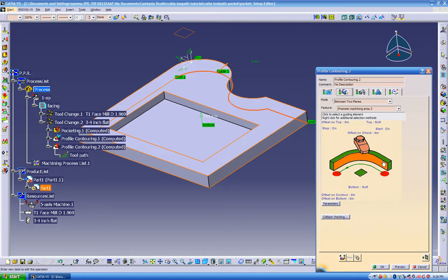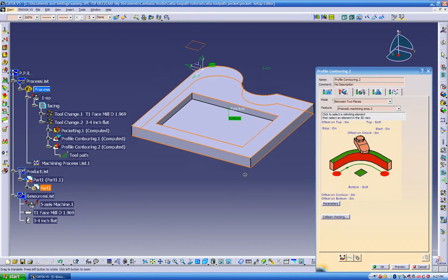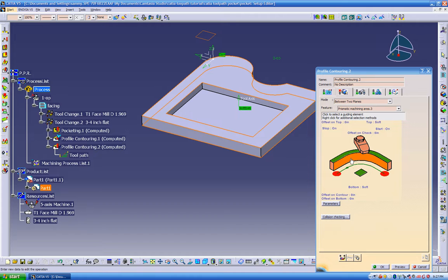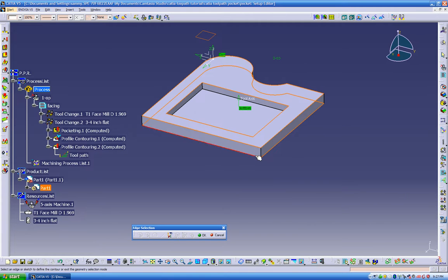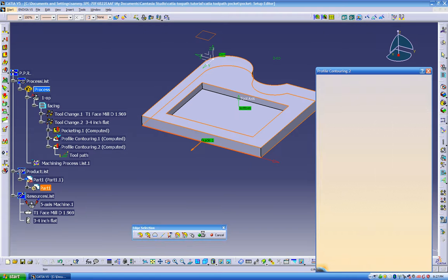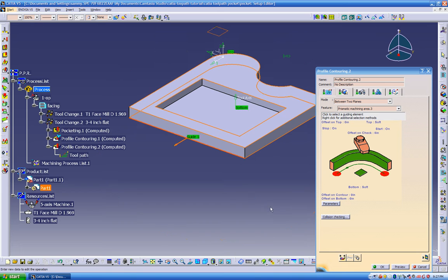The only thing we're going to remove is going to be those endpoints and this profile. We're going to leave the top and bottom the same because it's the same part, the same level. So let's do a right click and let's go back to remove all contours. Same thing to the points. We're going to remove this. And now we can go back to this wall and click on this edge. Let's click OK. And for now, we don't need to select this point. So already have everything selected.